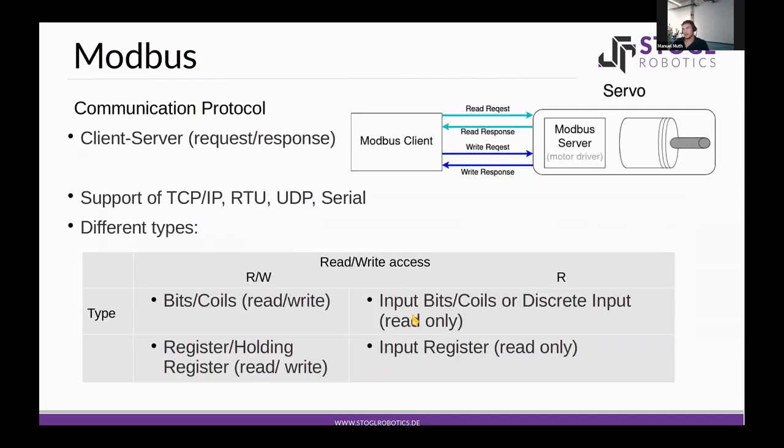And a little bit of background for Modbus, for people that are not that familiar with it. So Modbus is quite an old communication protocol, but still widely used for communication with sensors or servo motors. And it's based on a client-server architecture. So I've drawn a small simplified picture, which shows the most important stuff for us.